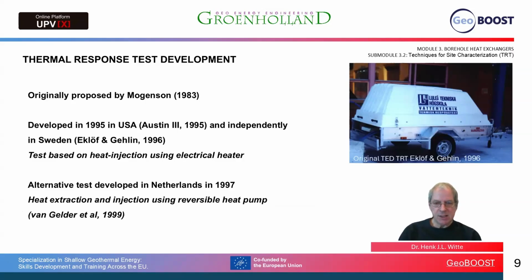Those tests, you can see an example in the little picture on the trailer. Those tests are based on heat injection using an electrical heater. An alternative test was developed in the Netherlands in 1997. It uses a reversible air source heat pump, and it allows you to do a heat extraction and heat injection.